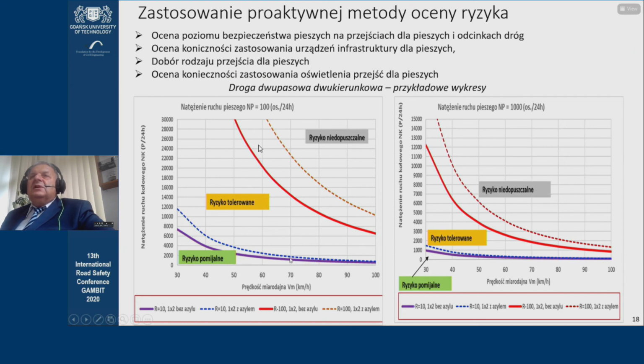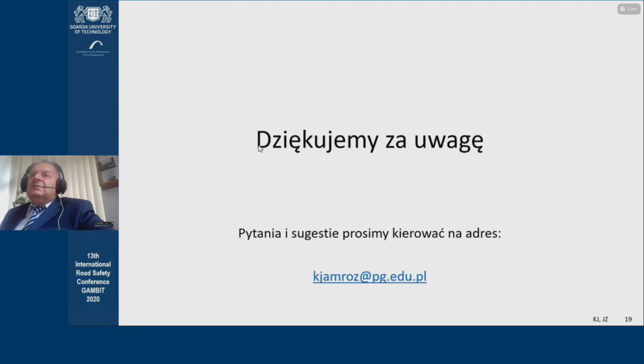So on some non-urban roads, it's 70 kilometers per hour with a volume of 5,000 vehicles, then we're off the scale. If it's 2,000, then we're off the scale as well. And that difference is crossing with an island, and this one is without one, so having an island helps a lot. And obviously, if it's a national road, then a zebra crossing wouldn't work at all.